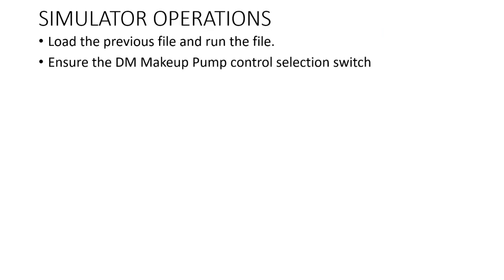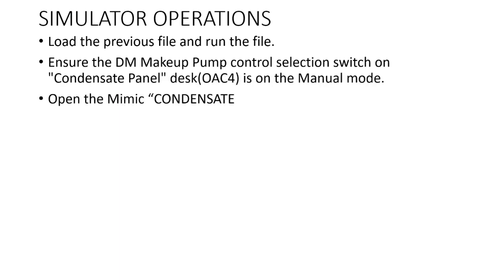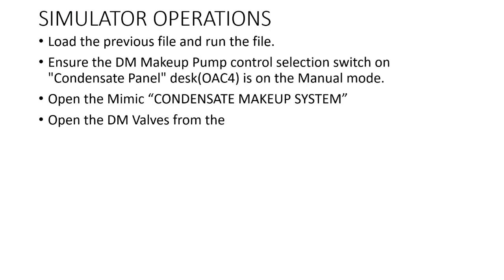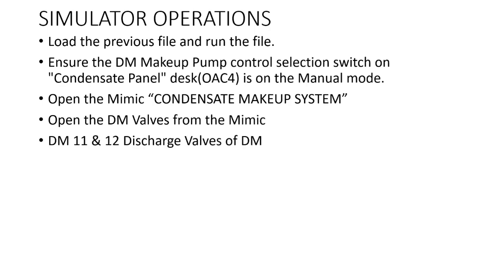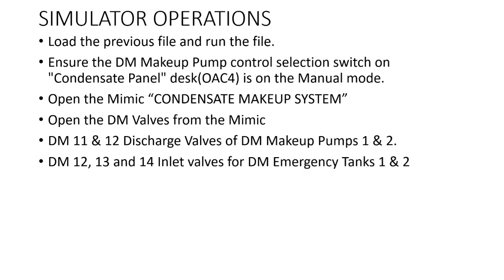Now the simulator operations, what we are doing: load the previous file and run the file. Ensure the DM makeup pump control selection switch on the condensate panel is in manual mode. Open the Mimic condensate makeup system. Open the DM valves from the Mimic.